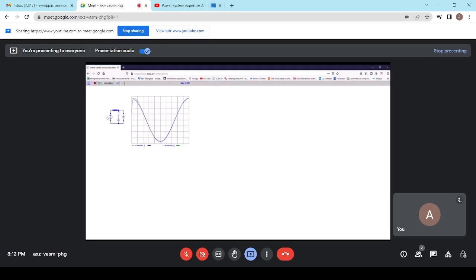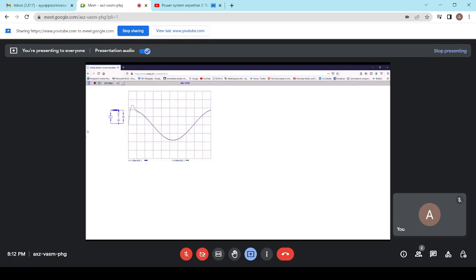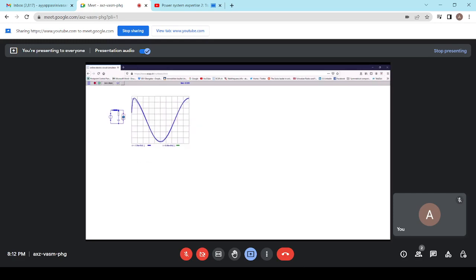You see, this is the source value and this is the TRV. TRV, by the way, stands for transient recovery voltage. I would like to have a kind of standard TRV, so I reduce the element here. I want to have an overshoot of 1.4 more or less. So this is what I would like to see on the source.